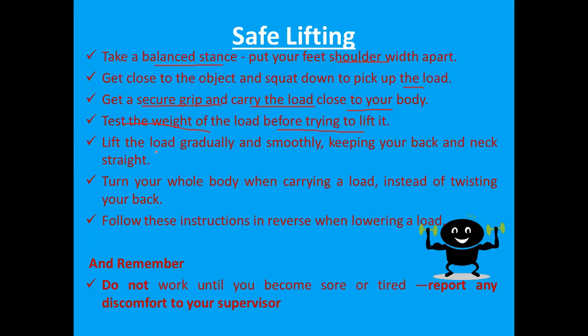Next one is lift the load gradually. Don't be in a hurry when lifting the load. Lift the load gradually and smoothly, keeping your back and neck straight. Whenever you are doing any process, you have to maintain your body posture accordingly. Otherwise, your neck and spinal cord will get problems.